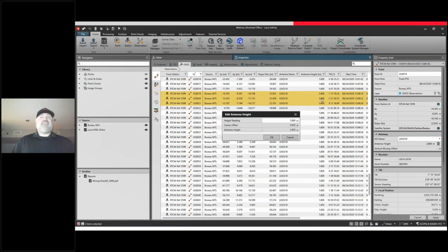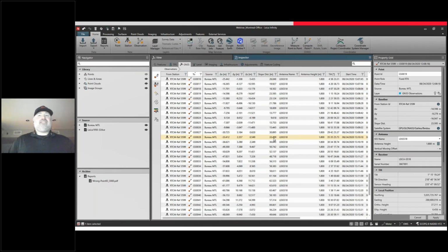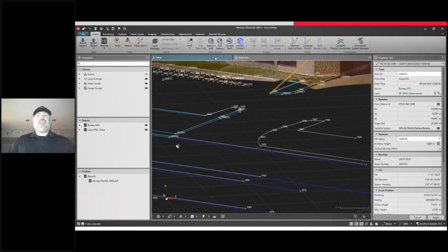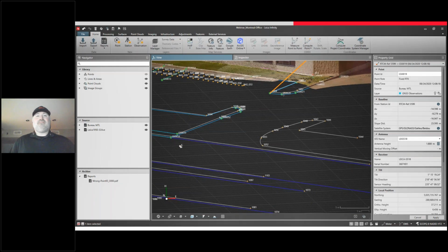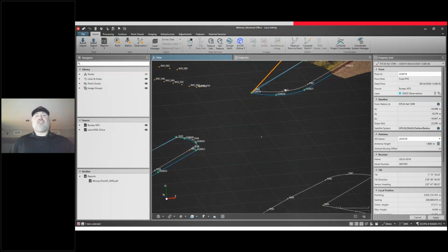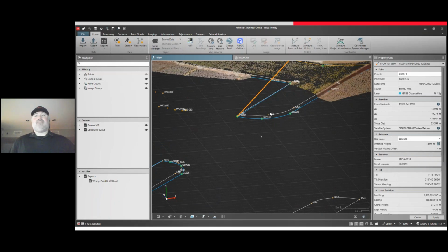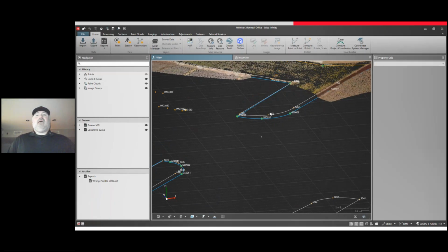Measurement data can easily be batch edited for most major field errors, such as antenna heights for GNSS and rod height and prism constant for total station measurements. The reason that this is important for GS18I data is that tilt measurements, when taken, affect both the horizontal and vertical position. And a standard ASCII fix to correct elevation data is not possible with GS18I data. It needs to be fixed inside of the Infinity software.